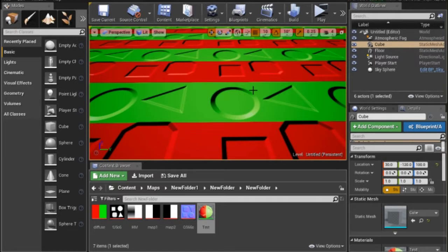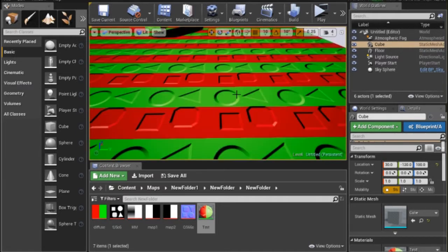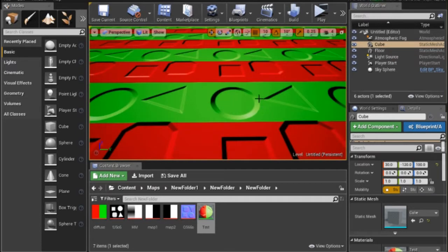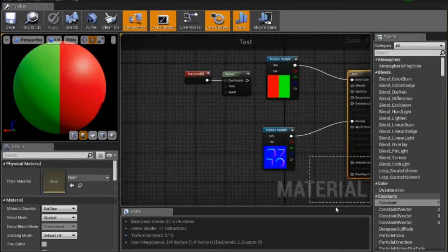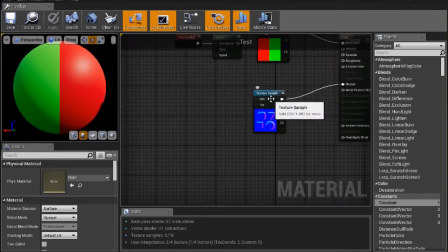So now if you don't want to have it going inside, but instead looking up, not like stamps going inside but looking up, then you have to rotate your normal map. You can do this if you go into your 2D software like Photoshop or GIMP and rotate it there, but you can also do it in here. That's what I want to show you.